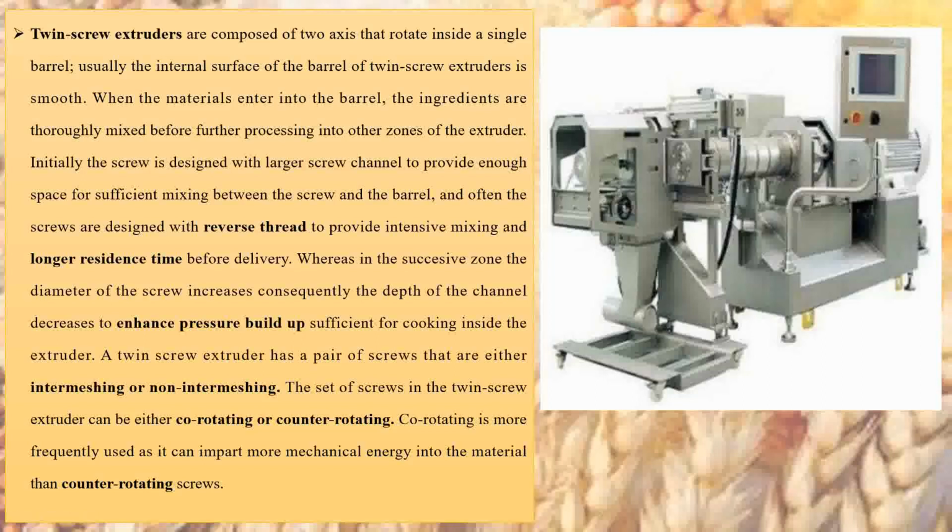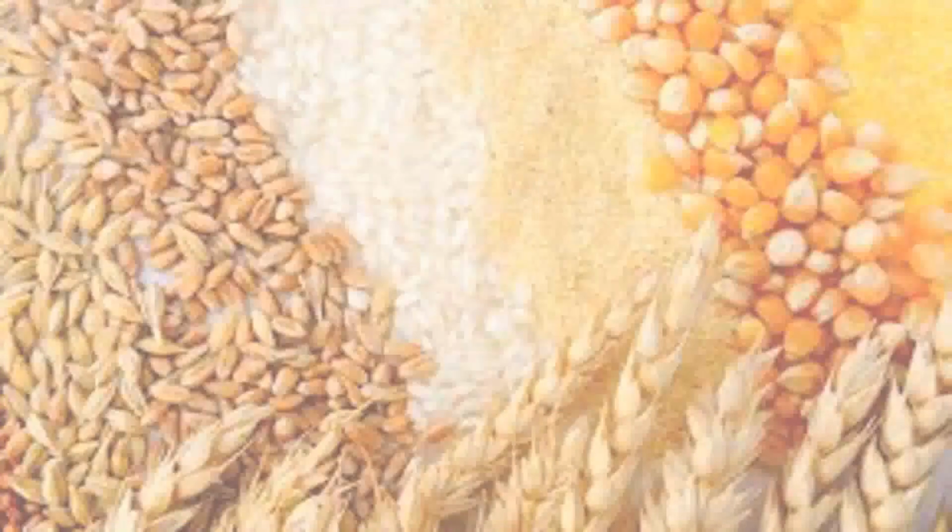If the moisture content is more, then the excess water is drained out, or in some cases the excess water in the single screw extruder is compensated by removing some of the set of premixed ingredients in order to keep the moisture content within the extrusion chamber in balance, so that it does not rise above 20%. Alright, so these are the pros and cons of the single screw and twin screw extruders.